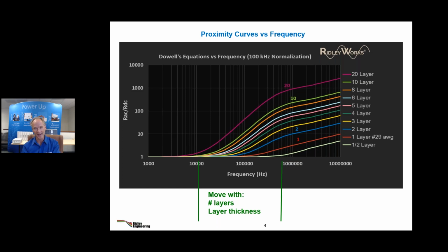And that's different to an LLC converter primary, so you're going to wind them differently in different cases. Hopefully that will come across when we do these examples. So we've got our little levers to move these curves here: the layer thickness, and the number of layers, moving this up and down.